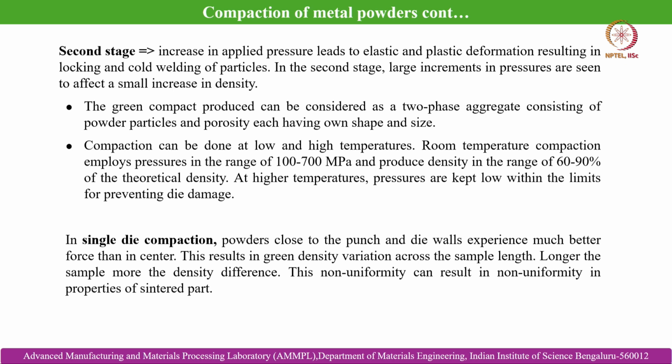In the second stage, large increments in pressure are seen to affect only a small increase in density. That is not the intended goal. In the second stage of compaction, the goal is to achieve cold welding between the interparticle connection points. So the first stage is basically to bring the powder particles in vicinity to each other and arrange them in a particular mold cavity, and the second stage is about cold welding between the powder aggregates.